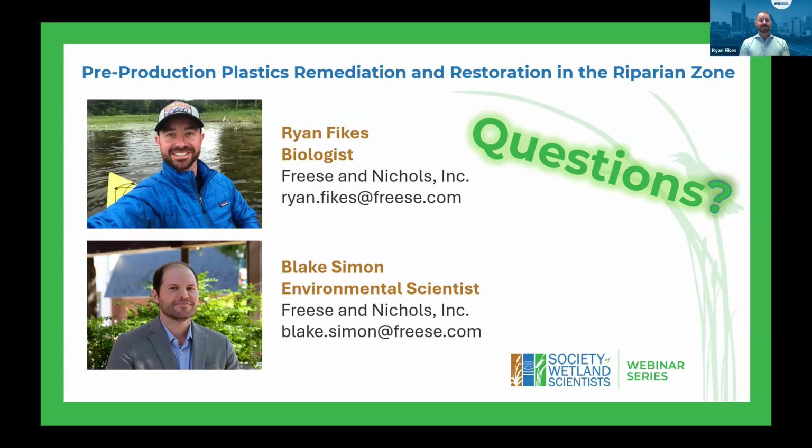It's another acronym we didn't have time to go into today, but some of the floating aggregate communities, such as I think I'd mentioned at one point, alligator weed, smartweed complex, that have these long trailing fibrous root systems, have a high tendency of aggregating floating plastics. On one hand, it's good because it holds them in that section, but that has resulted in the need to go in and do mechanical removal in places where there are also exceedances. So back to the previous question, we actually do drop samples on those areas within those aquatic communities, extrapolate out the number per cubic foot, and then if it exceeds, we'll go in, boom those off, and then mechanically remove all of that, which in most cases is invasive species, so we're happy to get it out of the system, but it does add effort and does require invasive species removal permits.